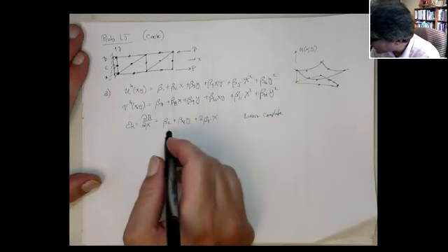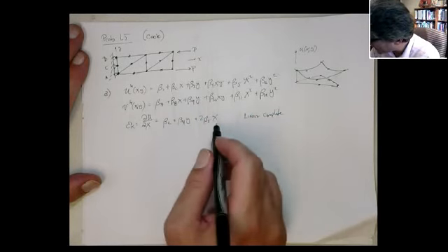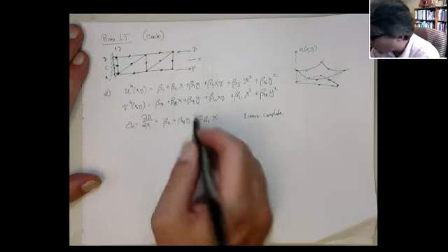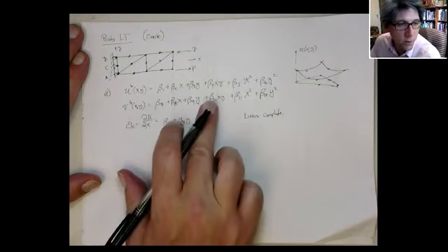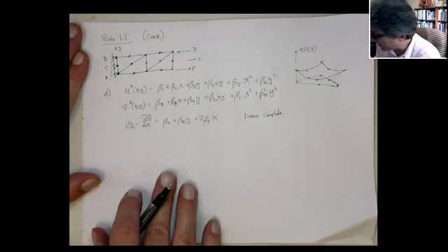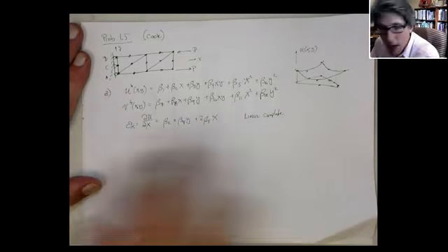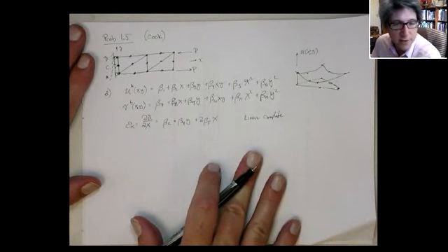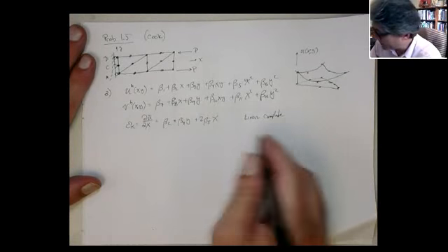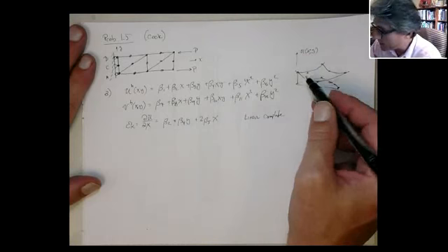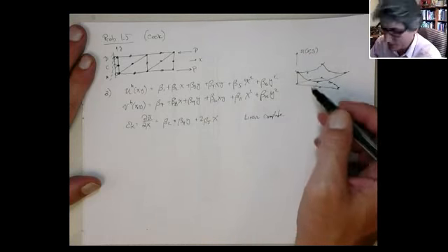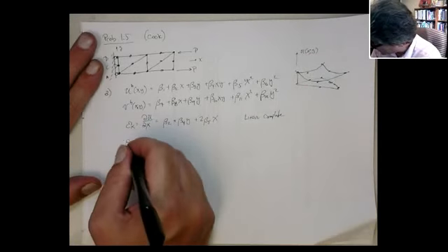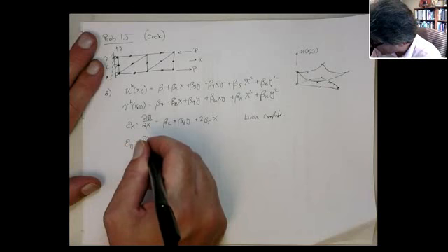We call it complete because it has the constant, the x term, and then the y term. All right? If we're missing one of these, it wouldn't be complete. Okay? But this means it can reproduce any linear polynomial in strain. All right? So in fact, this allows the strain to be reproduced as a plane. Okay? Okay, we do the normal strain in the y.